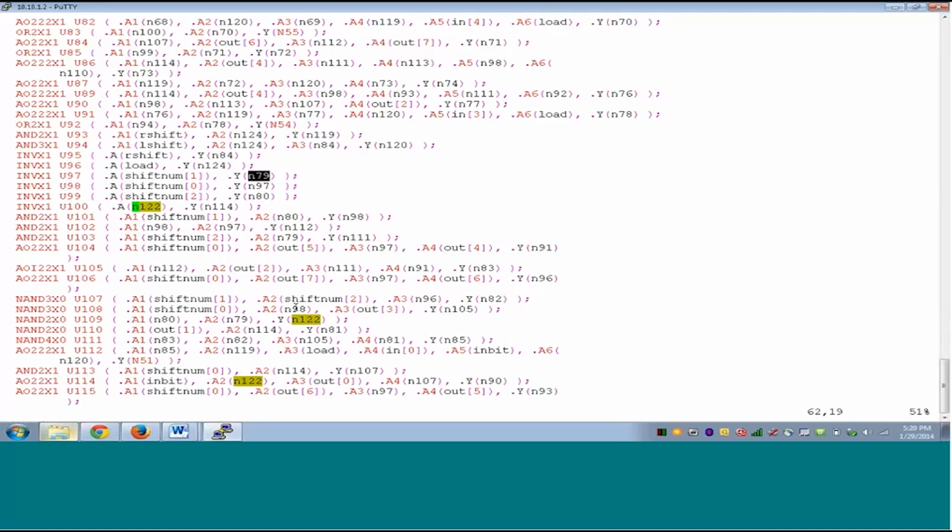So if we go back and draw it on paper, you would see the RTL condition we were talking about, that load being 0 and shift num being 0 and the block being in L shift or R shift mode, the same condition DC utilizes to generate EN. So if the condition is true, for the case where feedback is enabled, DC will switch off this clock. And the dynamic power is saved.